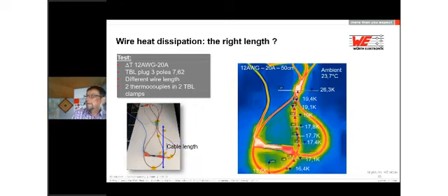There you can see the connector heats 26.3 Kelvin. It's all right, it's below 30. And the cable, which is close to the connector, has a temperature rise of 19.4 Kelvin. And this goes for a long time, and then sometimes it drops down to 17.8 Kelvin. But what about if we use a really quite short cable?